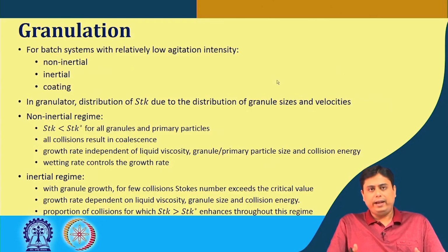This wetting rate is actually what controls the growth rate, and that is why in the last slides it is mentioned that when the saturation goes beyond 100%, when the liquid comes up on the surfaces, it drastically changes the growth mechanism.